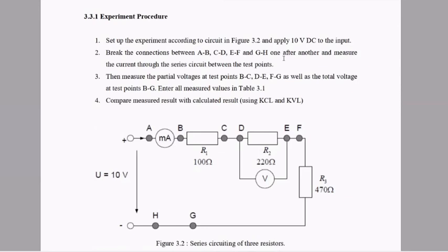Okay. So basically, like the previous lab session, we will get a slightly different measured value compared to theoretical data. So we need to know the actual value of the resistance, because one of the main things that affects the measurement is the resistor. Even if it's written 100, the actual value is not actually 100 ohm.